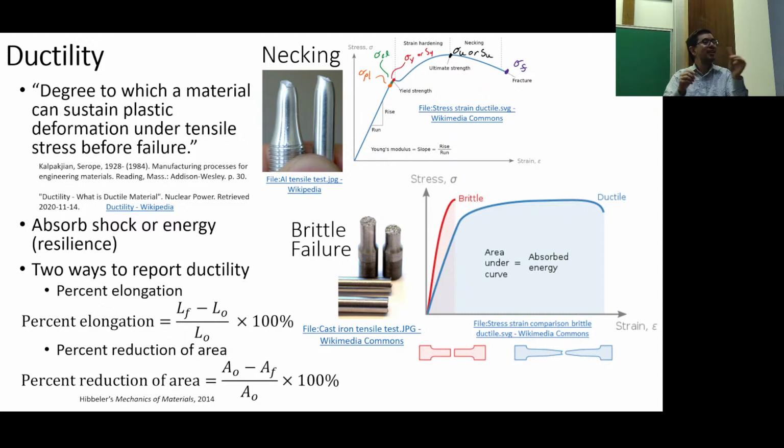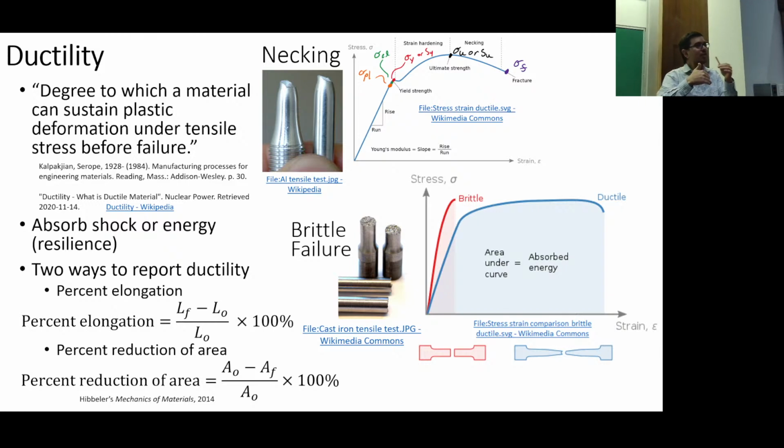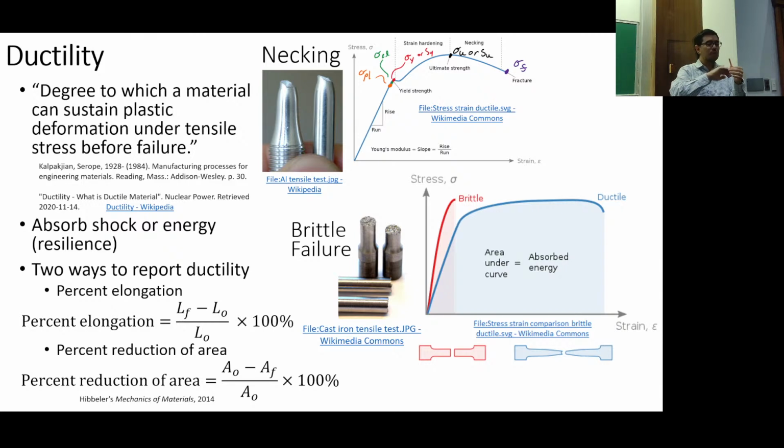Yes? Bending. That's bending, right? So we've done bending. Part of it is going to go in compression and parts of it are going to go in tension. We now know this, right? There's going to be a longitudinal axis, and a neutral axis. If I do it like this, it'll be compression in the bottom and tension in the top.